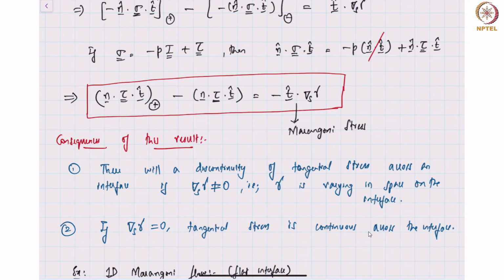So in regions where alcohol evaporates, locally the surface tension becomes more, and there you can create a differential surface tension, and such mixtures of two fluids can also lead to Marangoni stresses. All you need is a gradient of surface tension.